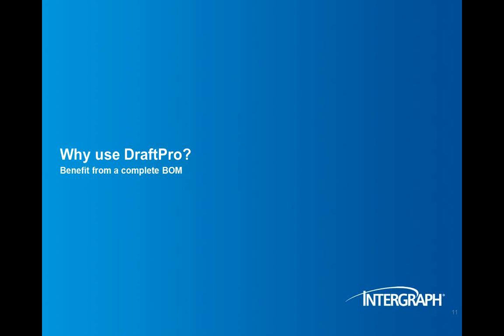By that I mean you can draw in plan, and CADWorx DraftPro has a tool in just 2 easy steps that allows you to take the plan model, create an intelligent detail, and create an intelligent elevation of what's in plan. Then you can fill in all the missing information and create an intelligent model off of that. We're going to show you quickly the concept behind the 2 easy steps that allow you to create not just a bill of material, but a complete bill of material for your 2D work.